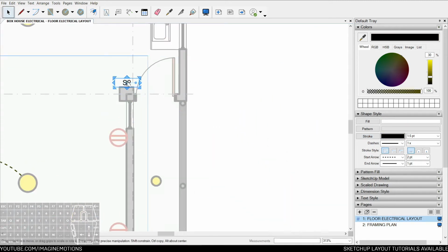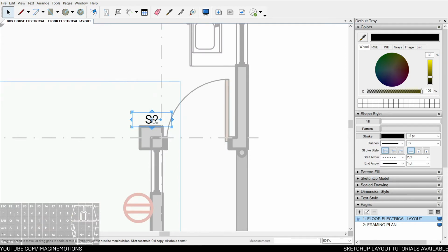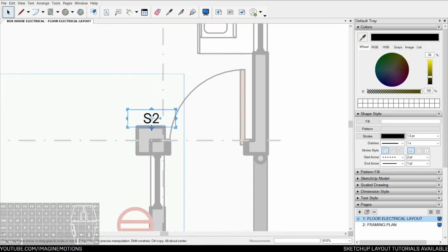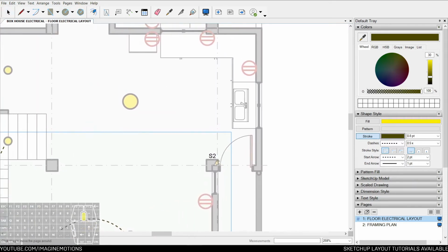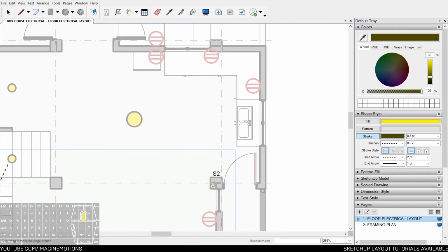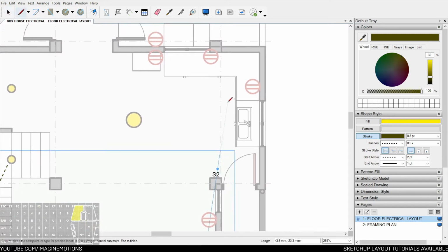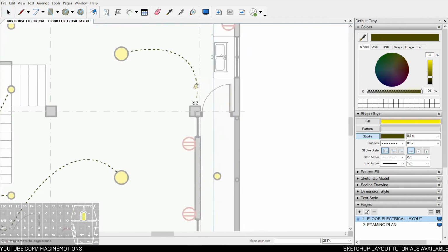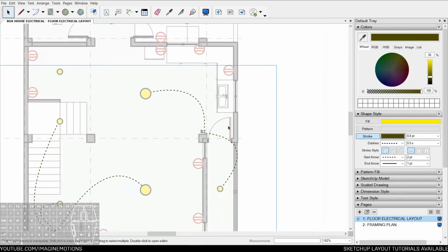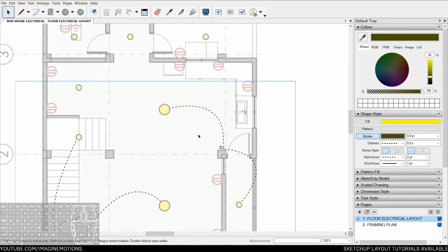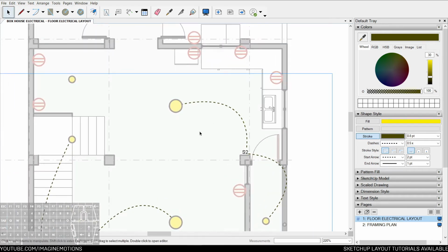Be careful though placing switches directly on the column because the switch pole or the conduit pipe might have to go through the beam, and that depends on the structural engineer if he likes to allow that, because sometimes they say it might compromise the strength of the structure compared to having it on walls where you can just hide it through the drop ceiling.